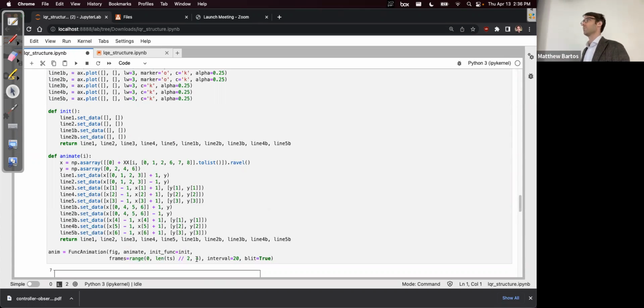In the case of Kalman filtering, that actually has a meaning, in that we're interested in the relative weight given to the sensor versus the model, but it'll still produce an estimated error bound from the Kalman filter, and that is affected by the magnitude of those weights as well as the relative magnitude. So it does have a meaning in this case in terms of the total cost incurred, essentially.